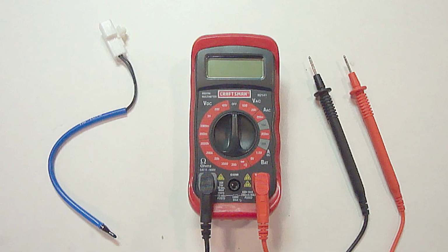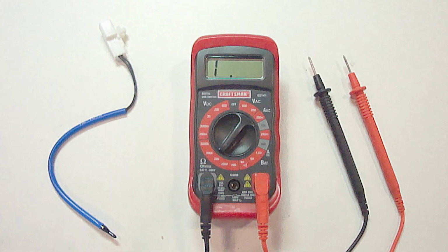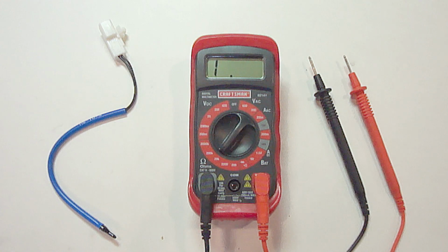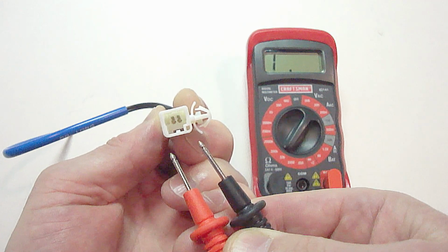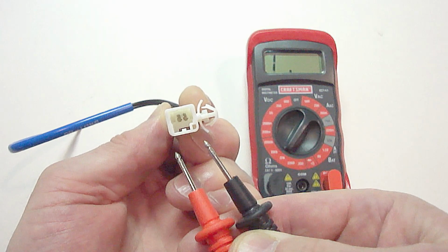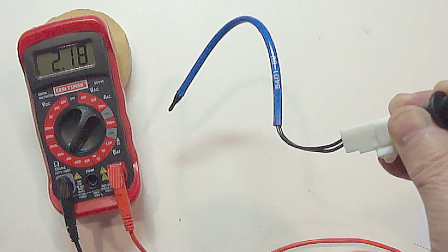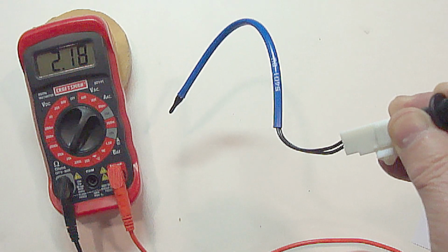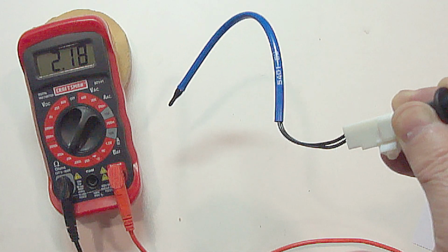To test the sensor, I'll turn the digital multimeter to the 20K or 20,000 ohm position. Next, place the two test probes on the two electrical contacts. It doesn't matter which color test probe goes on which side. Usually these sensors will show a plus or minus reading of around 2,000 ohms at a room temperature of 65 degrees Fahrenheit. As you can see, this sensor reads